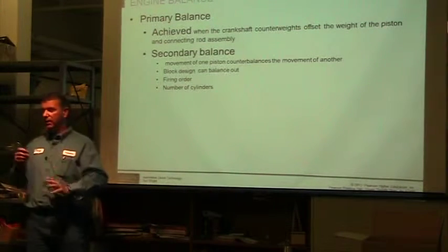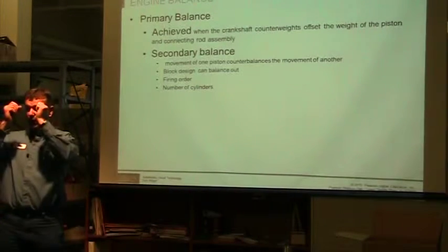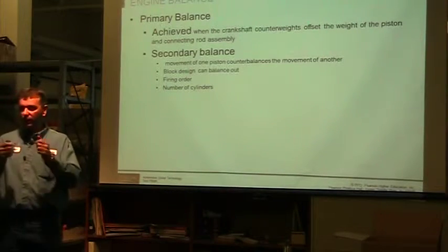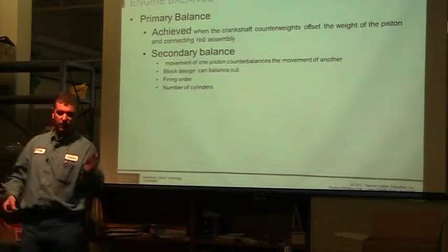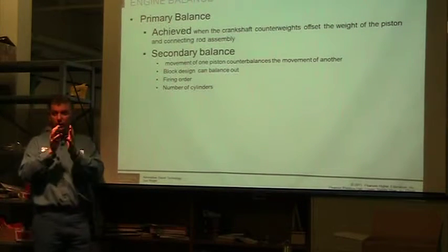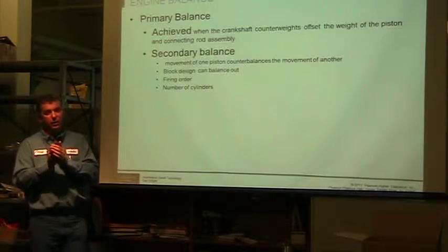Less vibration, less force because you have less compression, and then the torque out of a gas engine is not as much. So our counterweights are a little bit sloppier, a little bit lighter. In a diesel, it's very critical. So we have it on both sides, they're fairly even, and we're trying to keep them balanced. So that's your primary way.